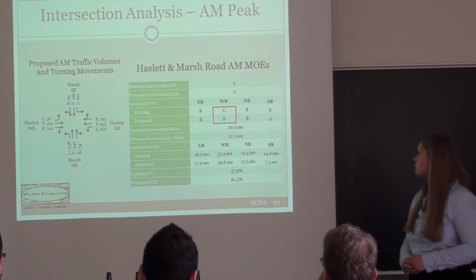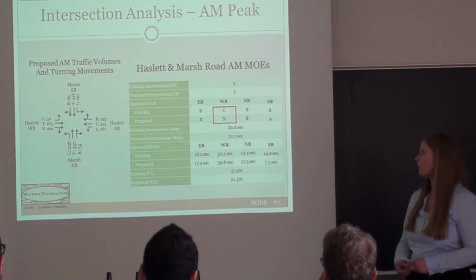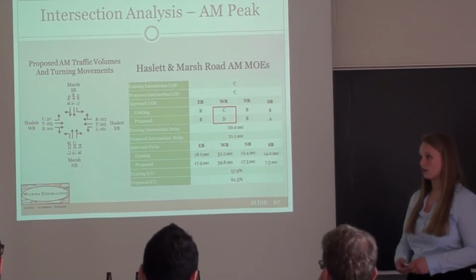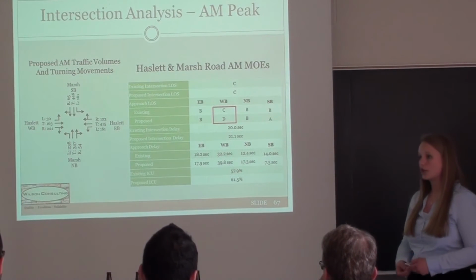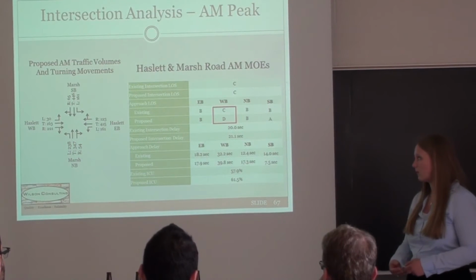And this was done using Synchro 6 analysis, and we took the existing traffic counts that we have, 2014 data from the Ingham County Road Department for the intersection, and then the driveway was done using just the traffic counter in order to calculate current driveway. And we did distribution depending on which way the cars were turning out of the driveways, if they were turning into the intersection, and then which driveways were utilized how much.